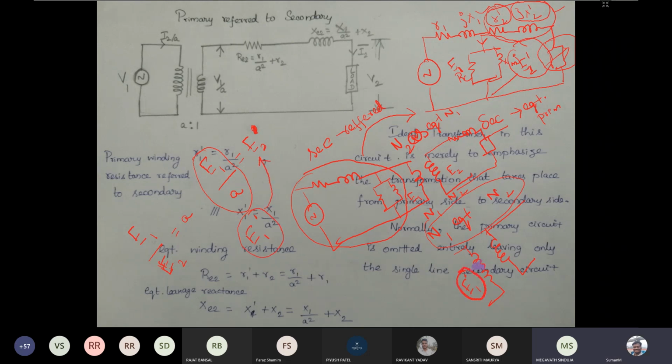So once we got this voltage, like the earlier case, the losses before and after this modification should be the same. So accordingly, we should change the series resistance and inductance values and the shunt element values. We have to change the shunt element parameters also. Accordingly, we have to change the source voltage also.